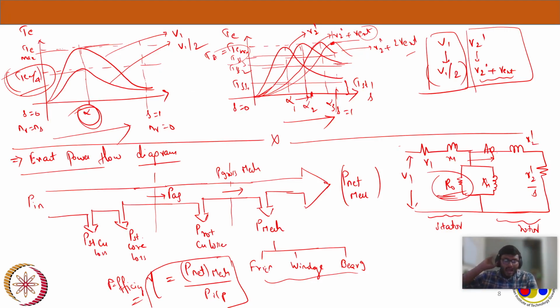Now see, once you have enough power at the shaft end, you will put some load on it, and your motor will rotate the load. But there is one condition, the no load condition, where you have no load present in the circuit. Let's say you have connected the equivalent circuit, connected the supply, and didn't give any load. Now, what power will the circuit take? These are the powers you see here. There are many losses in the circuit, and for all these losses your supply has to provide the input. So under no load condition, whatever the supply delivers is nothing but the combination of all these losses. When load is not there, whatever losses are present in the circuit, your supply has to supply them. So usually we say no load power means the combination of all the losses.